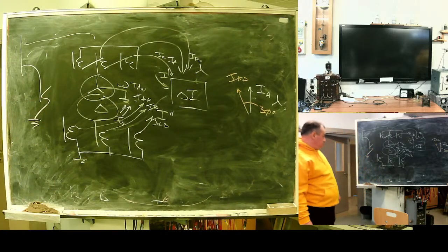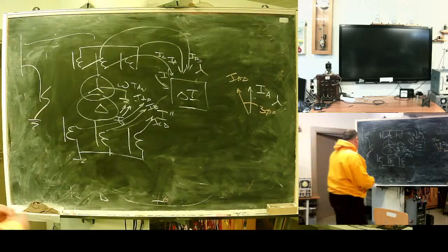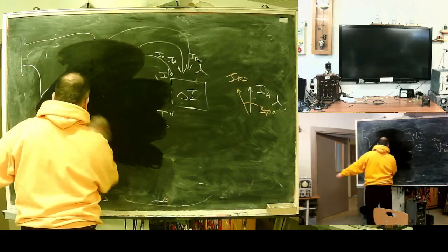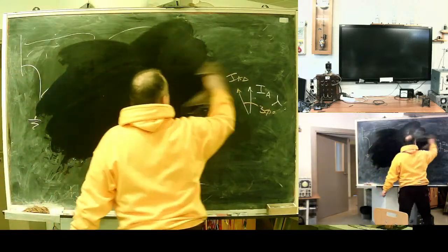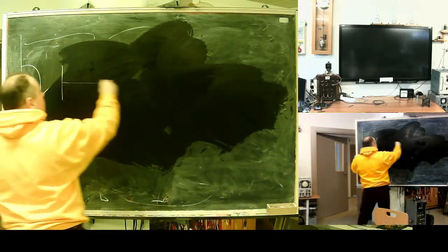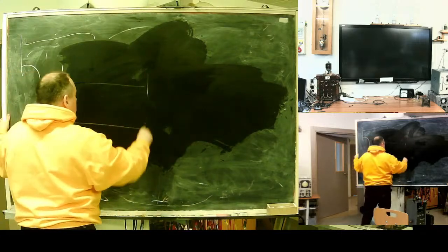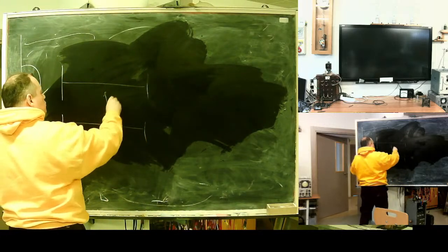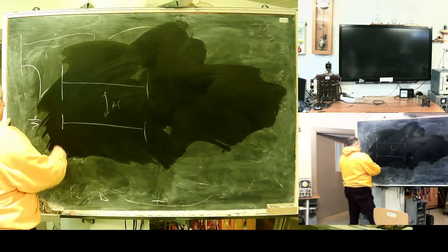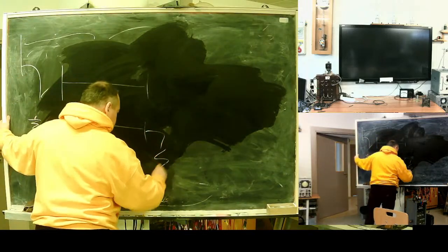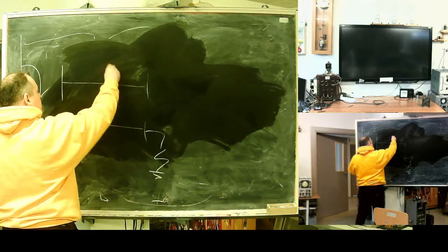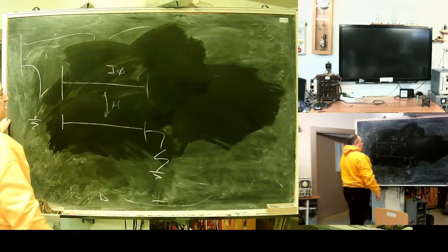Also, it's, how to say, a rare thing, but if you have parallel lines, they are close, so they have M coupling, magnetic coupling. Ground fault here due to magnetic coupling causes zero sequence current in this line.